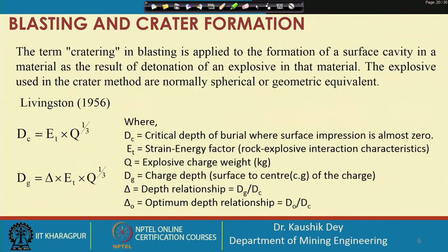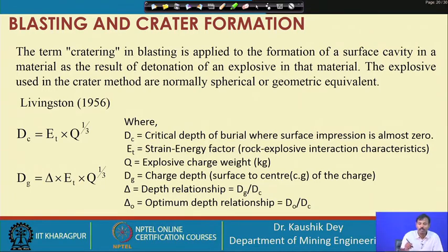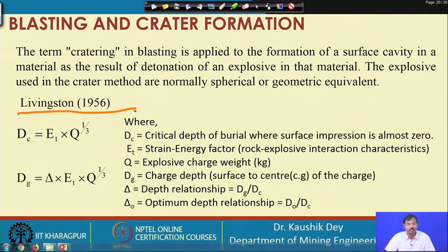A number of researchers have carried out experimentation on this. Livingstone 1956, as I have told you earlier, this is very important. Livingstone 1956 has generated some equations related to this. So, cratering is the term in blasting applied to the formation of the surface cavity in a material as the result of detonation of an explosive in that material.